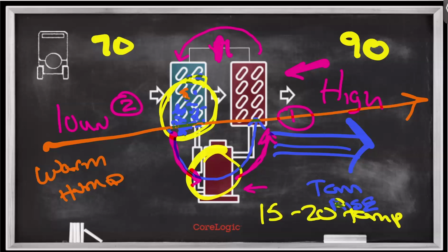All right. So this is a really easy way for you to analyze when you're looking at your humidity control and saying, okay, I've got way more moisture in the air than I expected. Humidity is increasing over time. Why is my humidity increasing over time? Then you go to your dehumidifier and you measure that dehumidifier to find out if it's working. And what you typically do to measure that dehumidifier to see if it's working is you look at this thing called grain depression, right? And that's where we're going to go next here in a second. That's one way of understanding if the dehumidifier is performing.